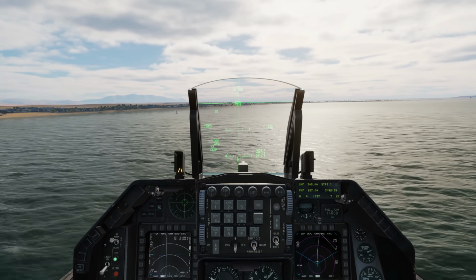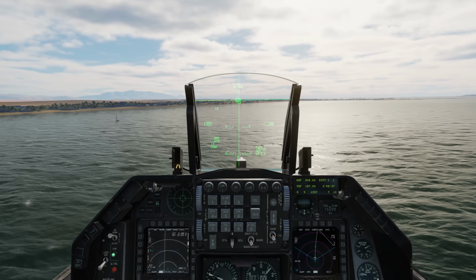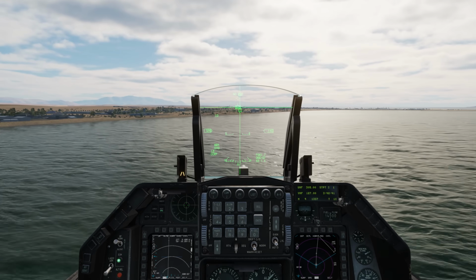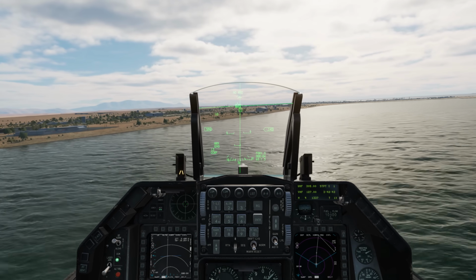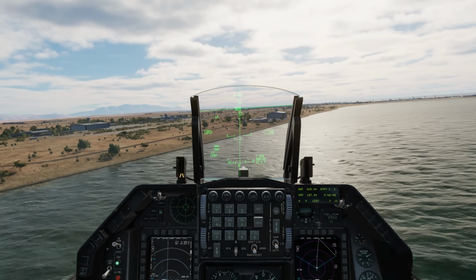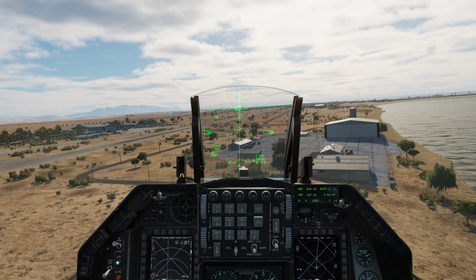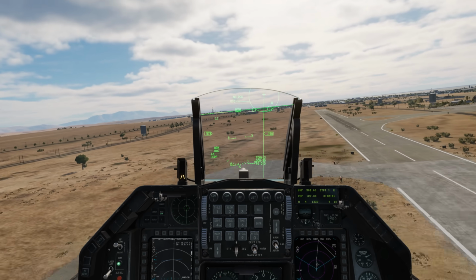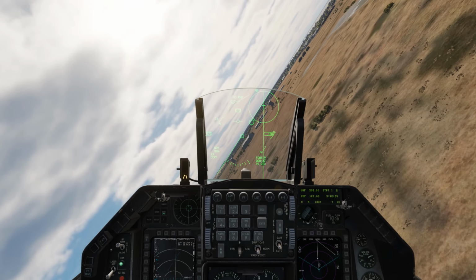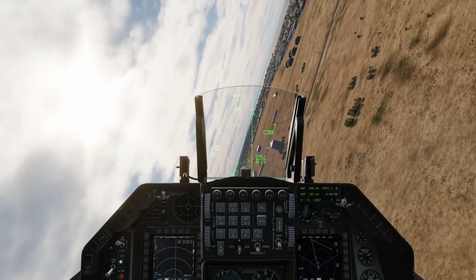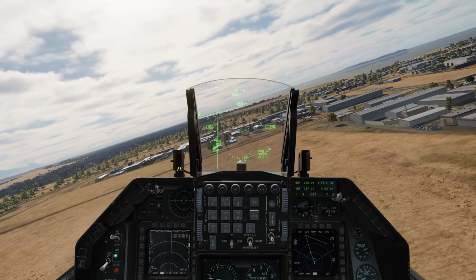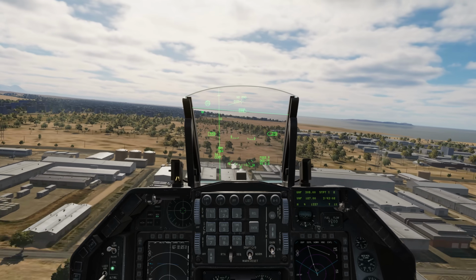Okay, approaching steer 1, and again, once I fly over, it should automatically sequence to steer 2. Okay, we can see our target point and our pull-up point through the HUD there. There is our RP. So I'm going to fly to align to that.